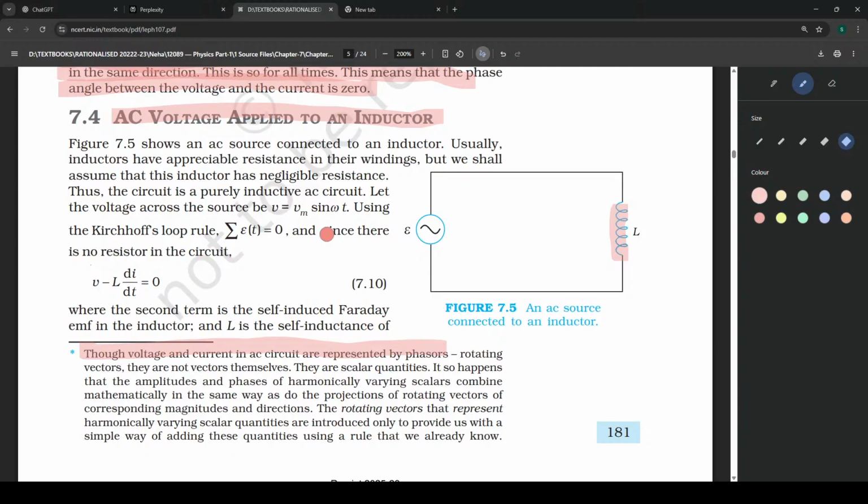Because it is an AC current, there is constant change in magnitude as well as direction. Even though there is no physical change of position of the coil, or area or anything similar to that, because it is an AC current, without any change in configuration of the coil, there will be a constant change in magnetic flux, because of which there will be self inductance seen here. And this self inductance will always be in the opposite direction of the current.